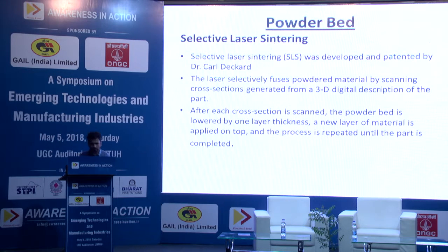Currently, the application for this particular technology will be jewelry. So why jewelry? When I'm talking about things like a small earring or even a small part where people are expecting a resolution of about 5 microns or 10 microns, this cannot be achieved in a normal FDM printer. A normal FDM printer, you can go up to 100 microns or maybe 150 microns.